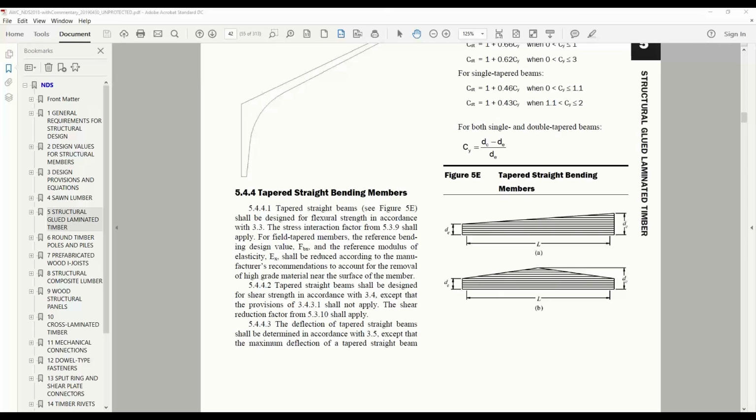Right. So just that balanced versus unbalanced layup. Typically when we're specifying an unbalanced layup, that's something we would see most commonly in a simple support application. Right, and if it's a stock unbalanced beam, you look at the multi-span tables. So you've got to read the footnotes and what the tables are for when you get into using tables.